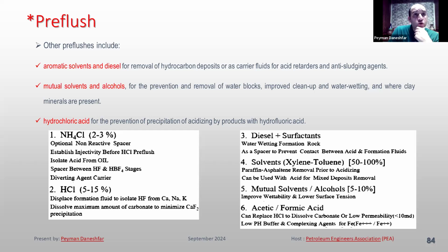And also, in an oil well, when we want to get a good result and better cleanup operation, it's better to use diesel at the first stage for the preflush. And also for water-wetting formation rocks, here you can see the 6 types of the preflushes.